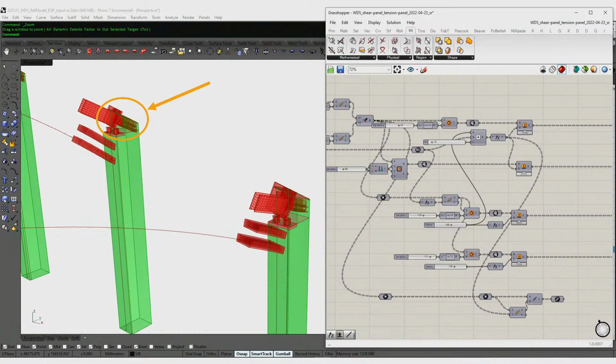So what does he do? We have on the column's head, for example, those connectors. Here we have to work with steel connectors, and every connector on these columns has a different inclination, different rotation, so every piece is unique. But no one wants to go in and model a unique piece. So they are able to do a script in the Grasshopper tool. The script is referenced to the parametric model, and all these steel parts are then generated automatically.